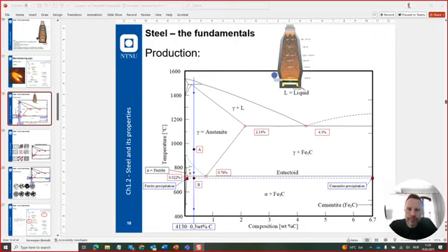At the bottom here, we have the percentage of carbon. This is 0.3% by weight carbon, and that produces a steel quality called 4130. It's just a mild steel, a typical mild steel, very often used in casing. And we'll go through what this phase diagram means to you guys.